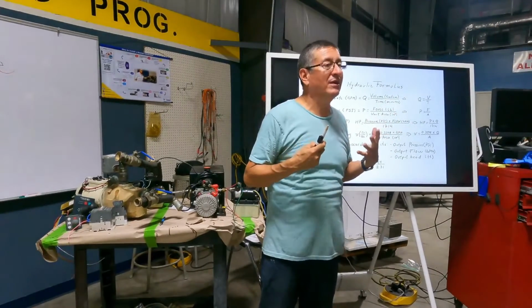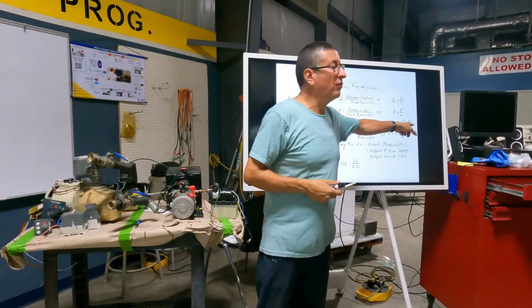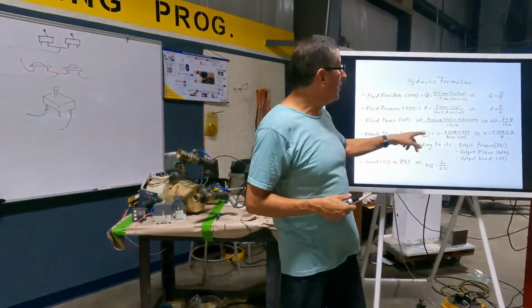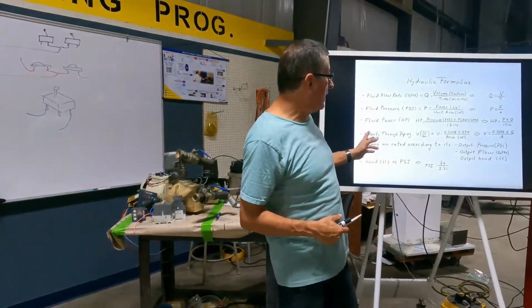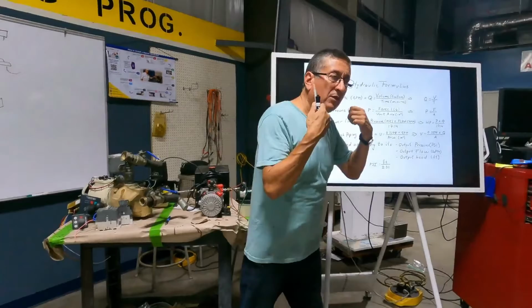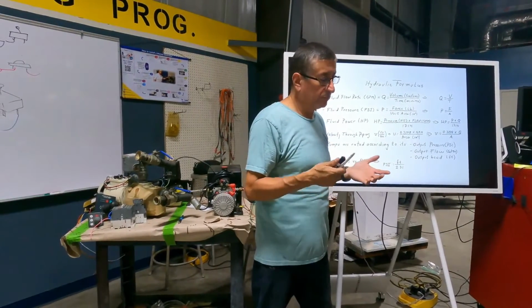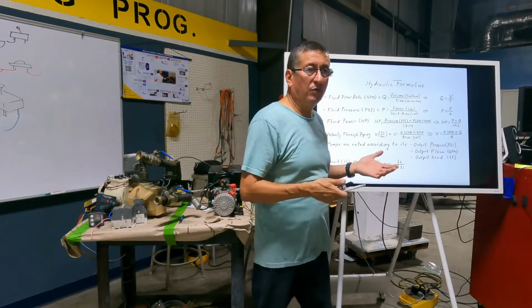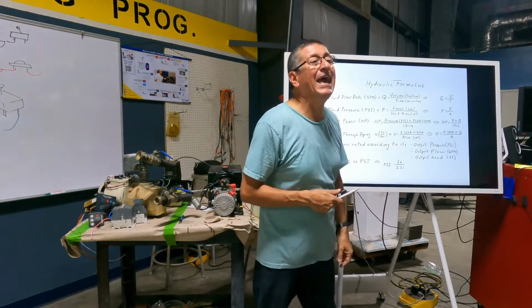One important thing that I need to keep clear is the horsepower. How much horsepower do I need in that new system? It depends on the pressure and the flow. The velocity depends on the flow divided by the area. And okay, when you select the pump, you need to provide to the manufacturer of those pumps the output pressure, the output flow, and the head.